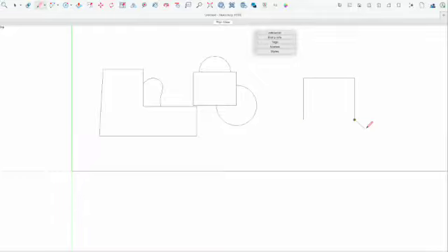While we're speaking of alignment, SketchUp is also able to extend a line in the same direction. So if you draw a line, but then realize it was too short, you just hover over the line, click down on the endpoint, and extend roughly in the direction you need to go. You'll see a magenta line appear, and that is the path to extend your line.